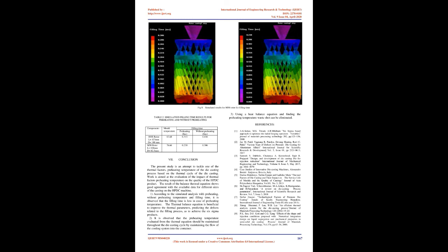The temperature of the mold can be controlled by regulating the flow of the cooling system through the mold. Fig. 5 and Fig. 6 show the mold temperature at a variable flow rate of the cooling system. So every time preheating is not required; we can set the required flow to maintain the mold temperature. The temperature of the mold is maintained for minimum filling time and life of the mold.